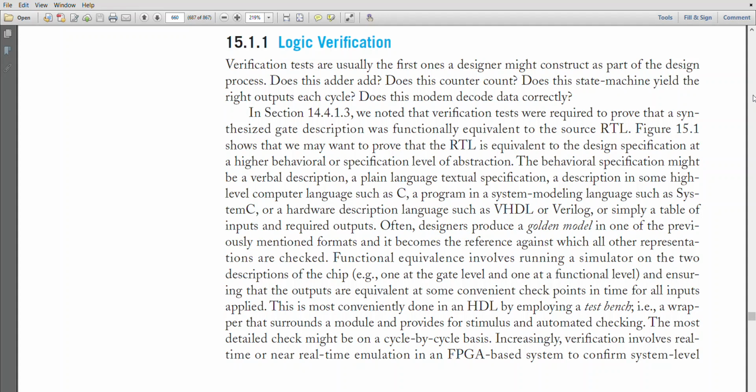The other important term along with testing in VLSI circuit design is verification. So it comes along with testing. So let me briefly tell you what is the basic difference between verification and testing first before we go ahead with this topic. Now the first thing you need to understand is that verification is done to ensure the correctness of the design, and testing is done to ensure the correctness of the device. This is the basic difference.